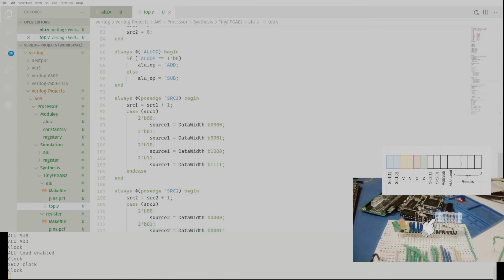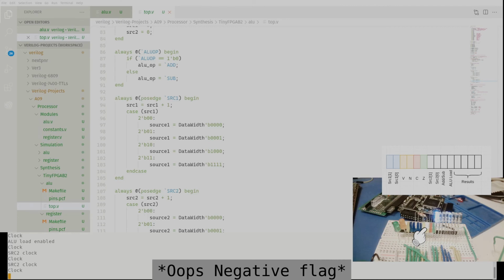So let's pulse S2 and switch to the next pattern. So come over here, we'll pulse S2, and now we're at the next pattern here, 1, 0, and we'll clock it. And as you can see, the carry flag went high, and that is because we actually added 0 plus 1, 0, 0, 0, and that caused the carry flag to go high, which is as we expect.